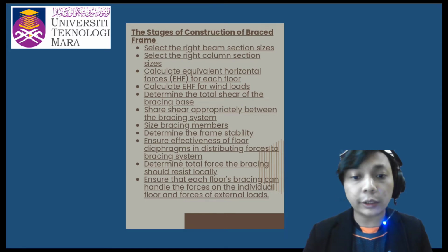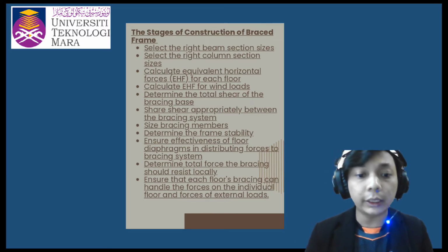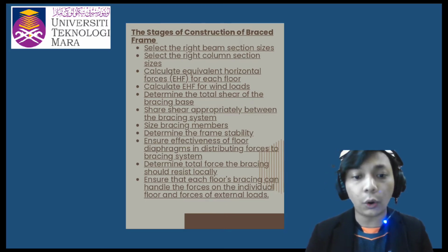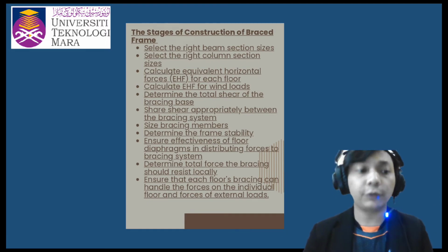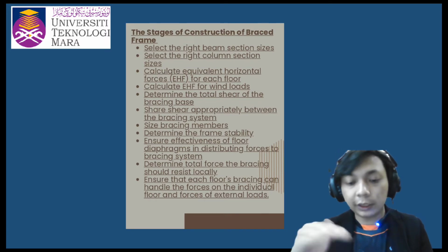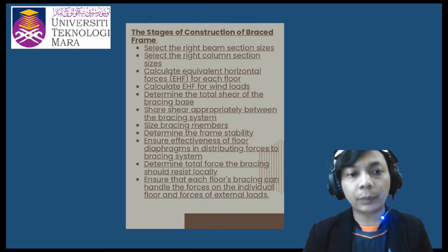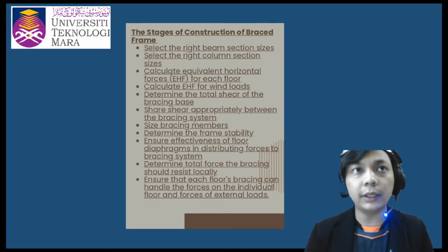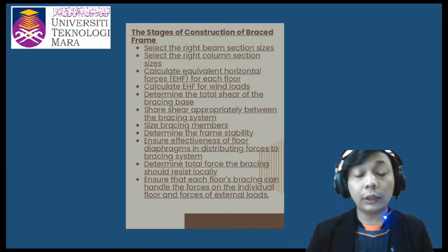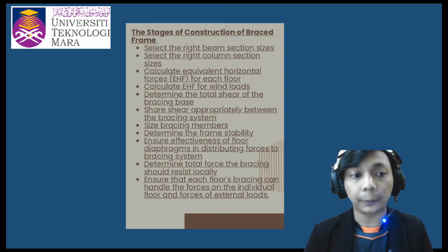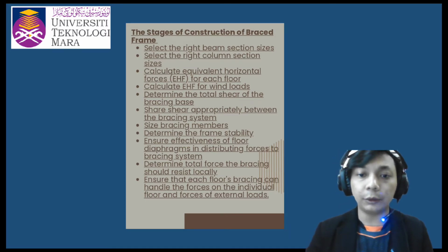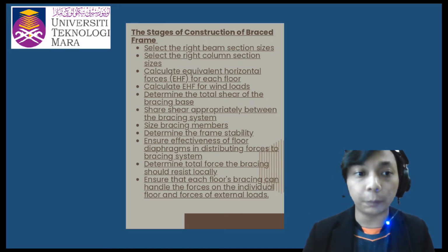Determine the total force the bracing should resist locally. Ensure that each floor's bracing can handle the force on an individual floor and the force from the external floor. With these steps, the bracing system can make a good building that can resist lateral force, so the structure cannot deform before anything. So thank you, and we move to the next topic.